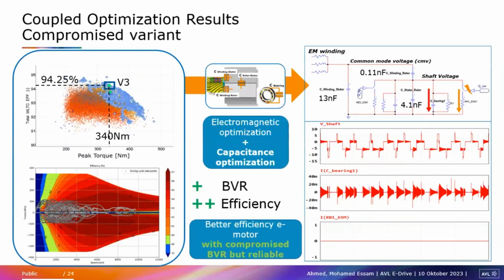create a lower impedance in parallel with the capacitance. So any current or any shaft voltage can basically get released in parallel, for example, in a conductive shaft ground ring, in conductive bearings. Tesla, for example, has a patent to use an auxiliary bearing, a third bearing, that is put there just to get all these discharges and currents in parallel.